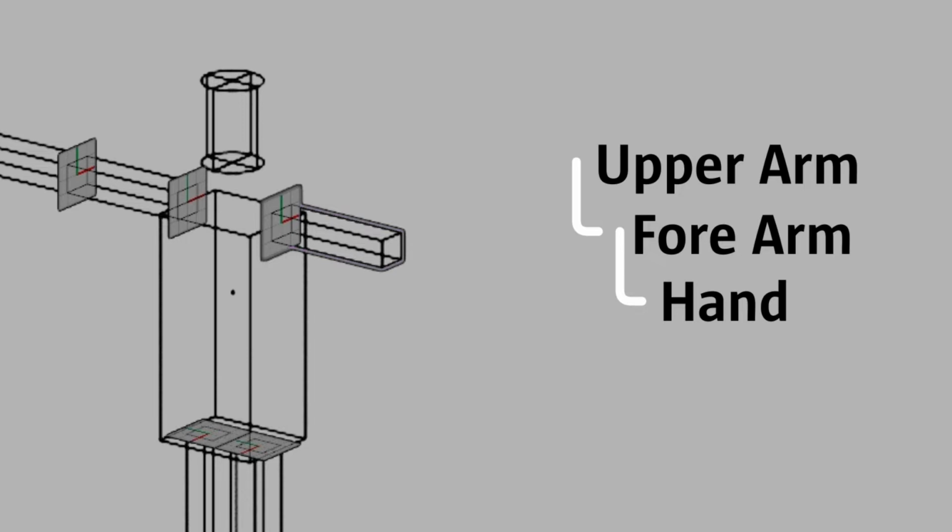First, we can set our upper arm box, and we will set the size and the rotation control, and then we will use our upper arm to define the base plane for our forearm, because we need our forearm to follow the movement of the upper arm. Then we will use this plane to build our forearm box, right?